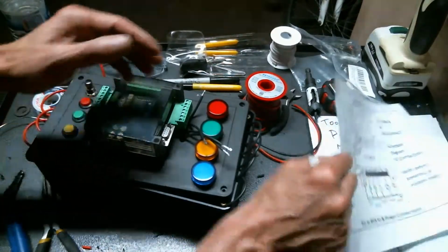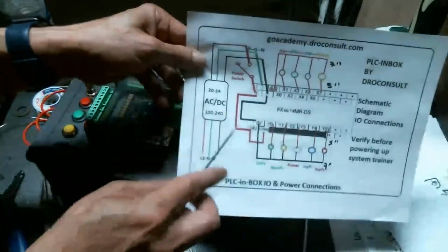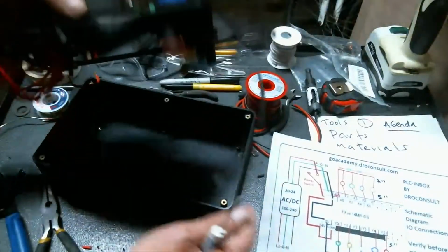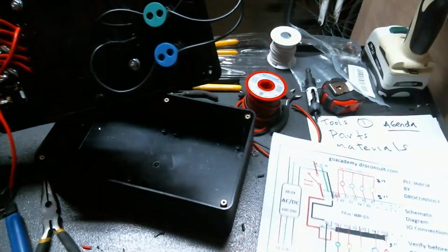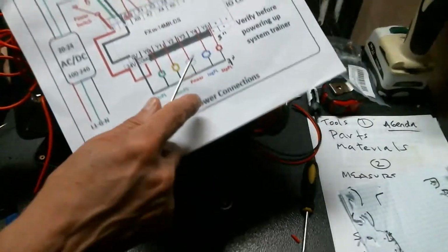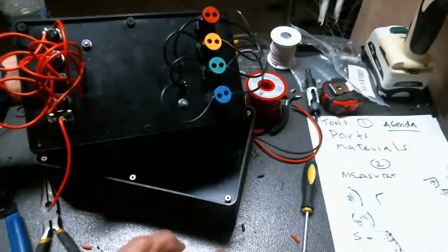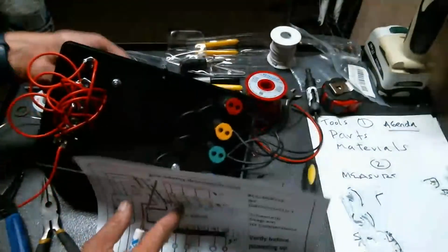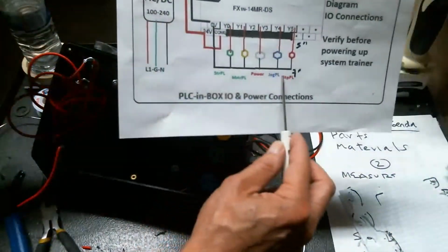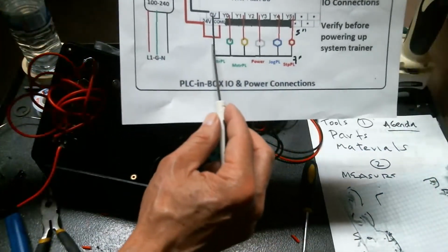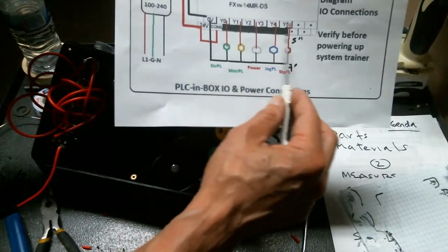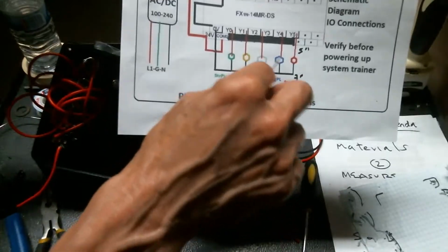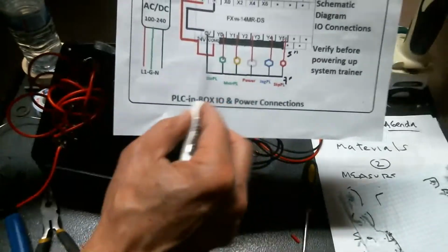All right, let's work the other side. Before we do this bridging here, let's work the other side. We already got the loop side of the controller. Now we need to connect this wire and the rest of the wires that connect from the output of the controller to the output wires, in this case, pilot lights.